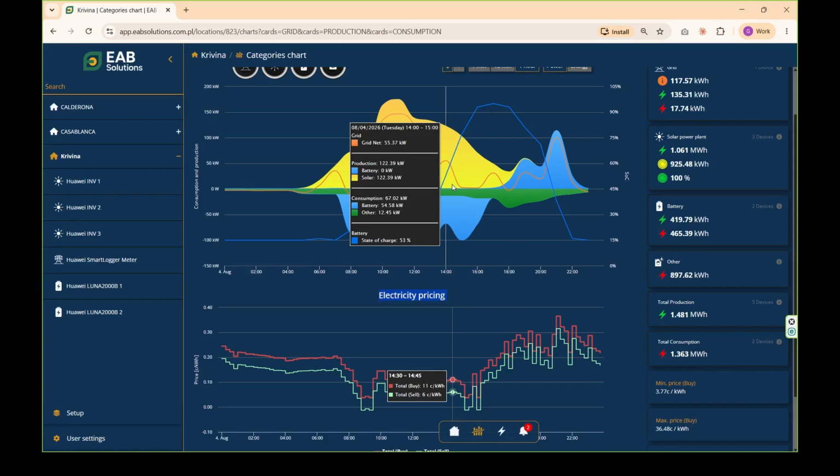What else can fail? Combinations of elements can fail. What happens if the PV fails? The PV fails, and, for whatever reason, the PV inverters don't work, whether for a few hours or for a few days. No problem. The battery is still operational, and the EMS is still operational. No PV production. It doesn't use it. Does it know the electricity prices? Yes. Does it have an empty battery to work with? Also yes. The arbitrage lever works. The power peak limiting lever works. The battery is able to limit power peaks, so those two levers would keep working.